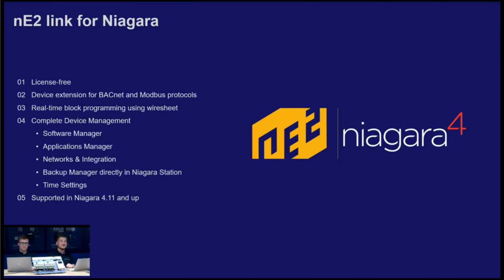And last but not least, of course, we have the RTC. On those controllers, you can set all the time settings independently, or you can just share it with the Niagara station. So it will take the time from your Niagara station. And the last feature, it works with any Niagara version starting from 4.11. That means you can use it in your workbench, you don't necessarily need to use our OEM IC workbench. You can go with Tridium, EMEA, or Vicon, or any other workbenches you're actually using.